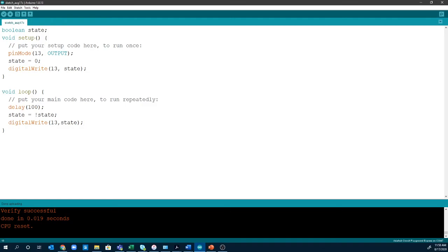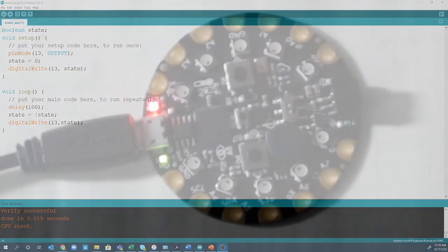You saw that error message flash really quickly. What that's for is the Arduino Adafruit Circuit Playground Express supports more than just Arduino languages. And so it's going to try to put it as a drive on your computer for using Python. Since you're not using Python, you'll hear it add that drive and then it'll immediately remove it. And sometimes you'll get just a small error about that and just click OK. But our code is now uploaded to our board. So let's flash over to our board.